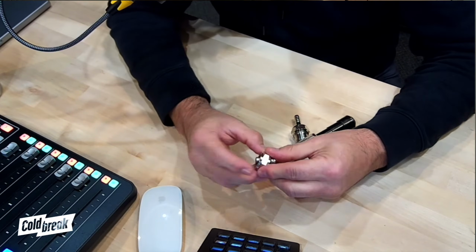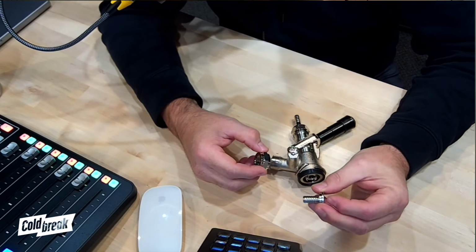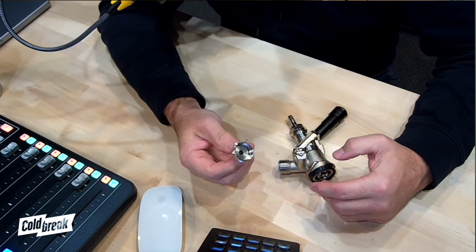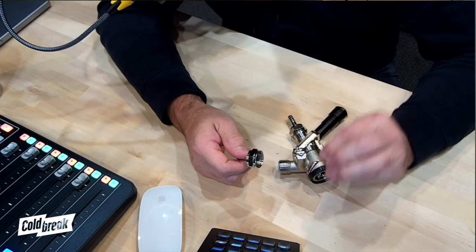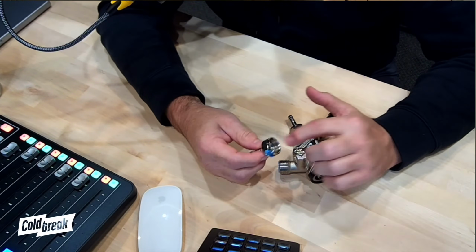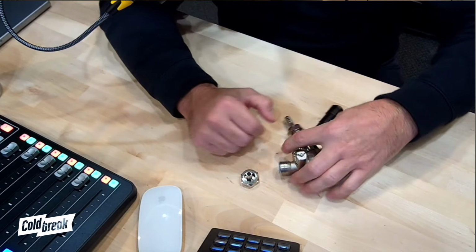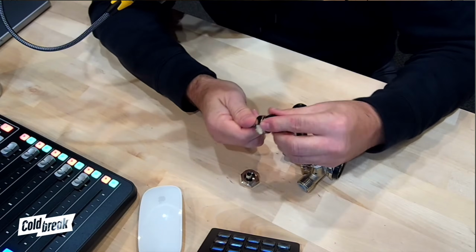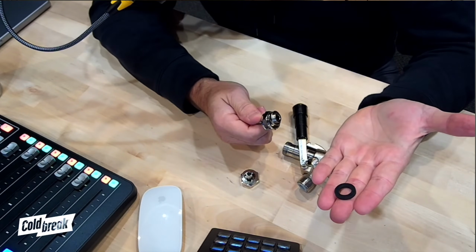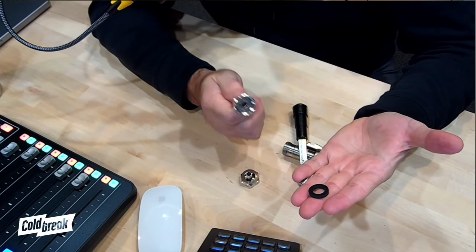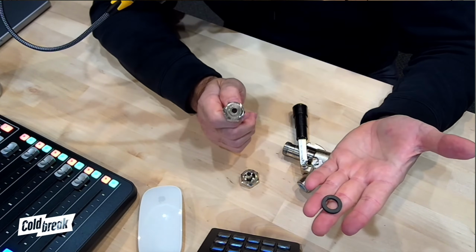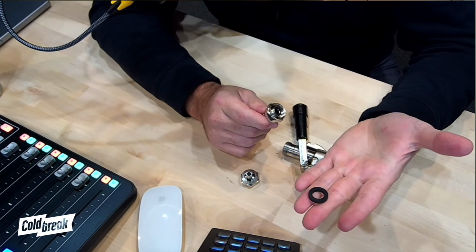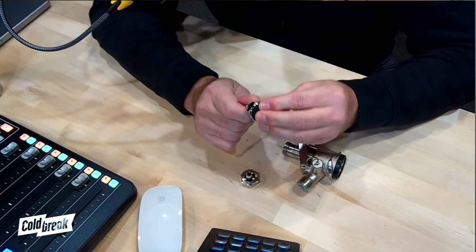These are tailpieces. These come in different sizes depending on the size of your tubing. This is a hex beer nut. In any draft system, it's all metal-to-metal connections, and anytime you've got that, you have to have some sort of rubber seal between any of these connections. So these are called beer washers. When you buy something like a jockey box, it is a very good idea to always buy extra beer washers because these get lost very easily. I always like zip tying them to the inside of a jockey box. That way I've got extras.